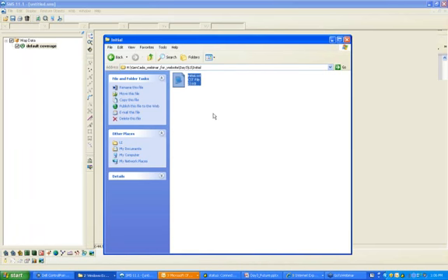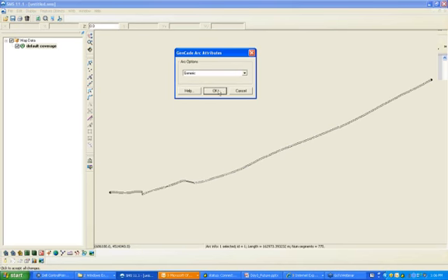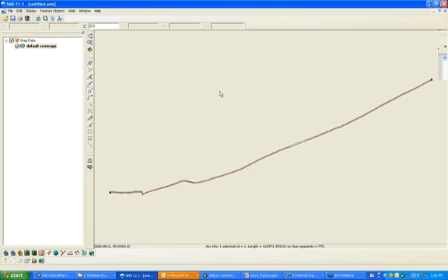So I'm going to go ahead and bring this into the SMS just by dragging it in. And again, now we just have a black line. It's very generic. And we have to go into the Select Feature Arc. So we'll click here, and we'll double click on the line, and we'll define it as an initial shoreline. And we'll click OK. So now it's turned green.